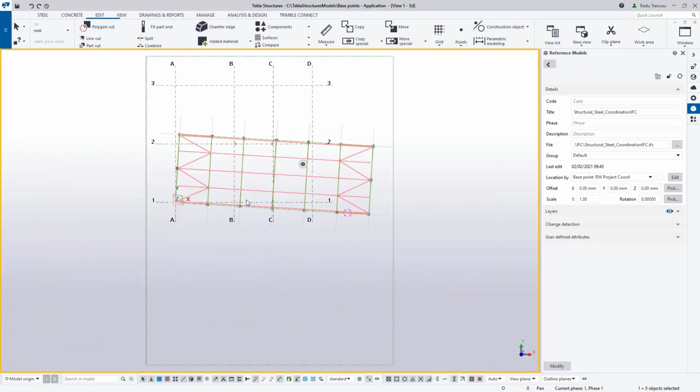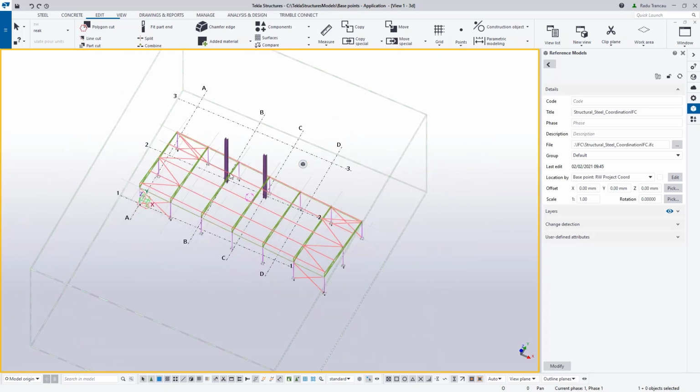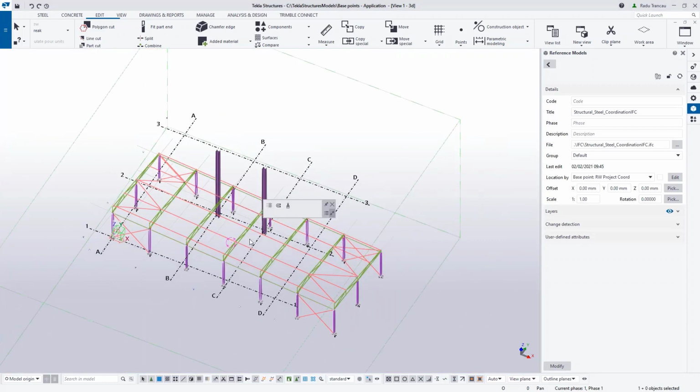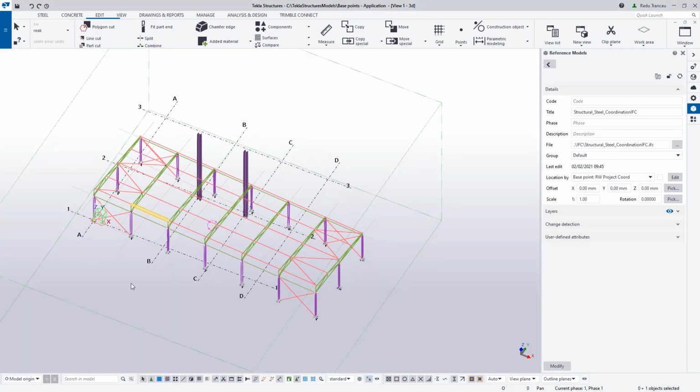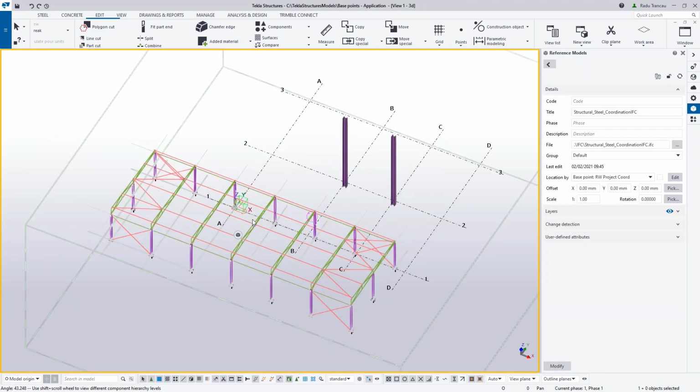Okay, so we've talked about importing. Now let's talk about exporting, and that's just one issue here. One mistake that I've seen people doing. It's not actually a mistake, but it's more of an omission to tick a short box. Okay, so to export in the same coordinate system, in the same base point, I will just quickly arrange the IFC to its real world project coordinates, just so that we have a flushed model, and we are using the real ones.